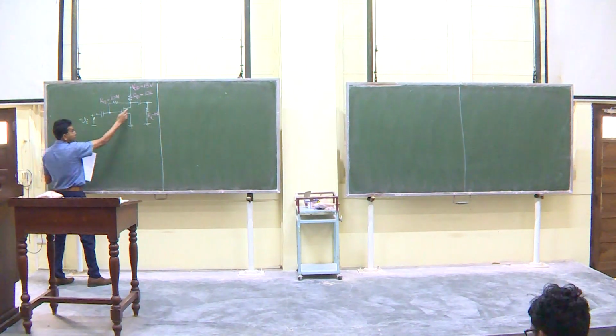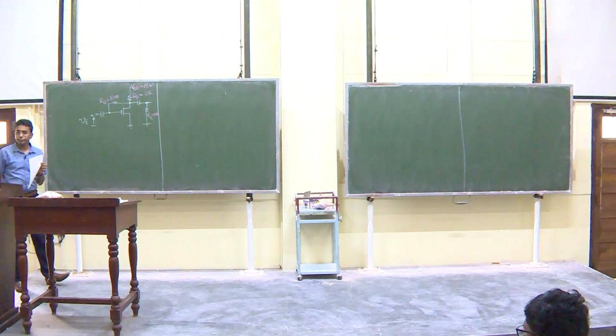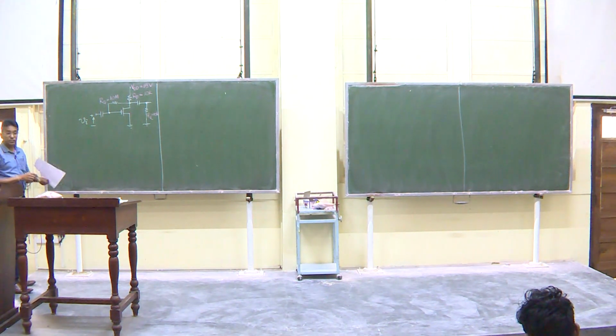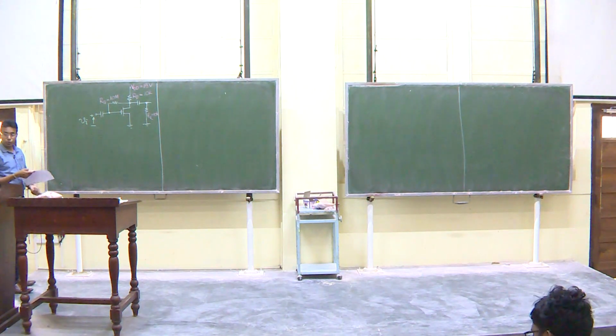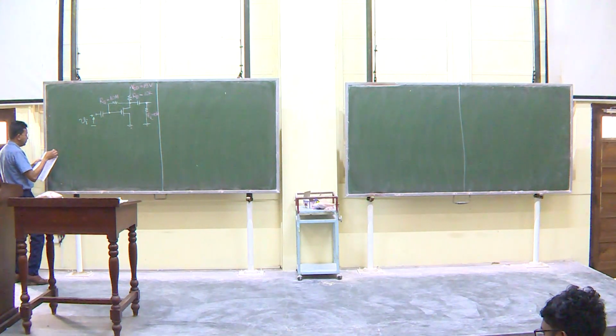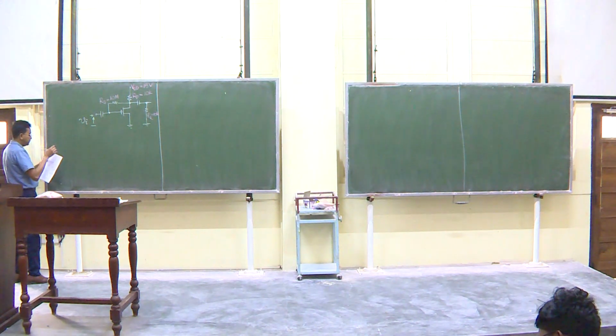These capacitors are considered large capacitors, so that they can be considered short circuits when it comes to the AC analysis, right? And open circuits for DC, right?